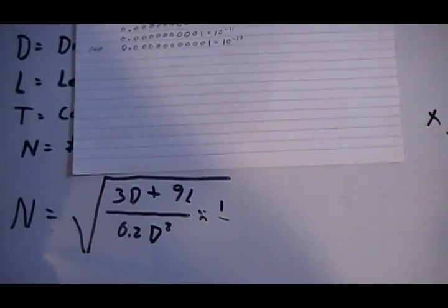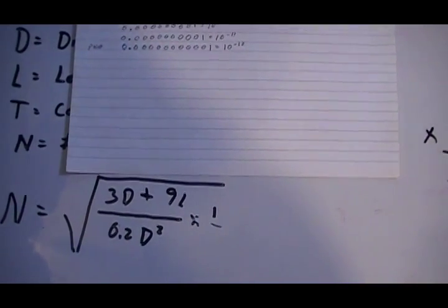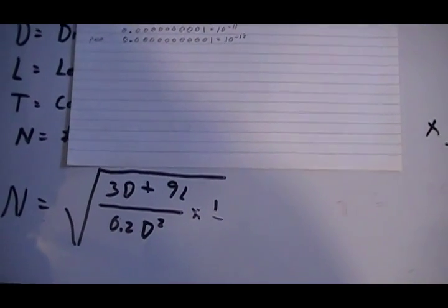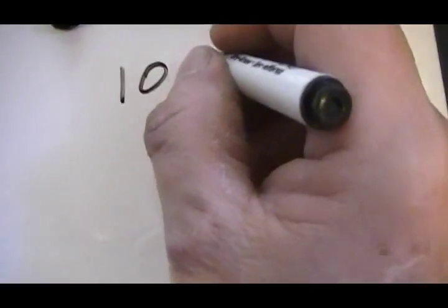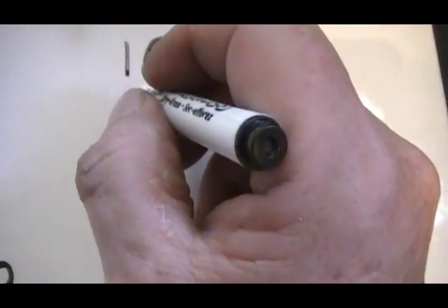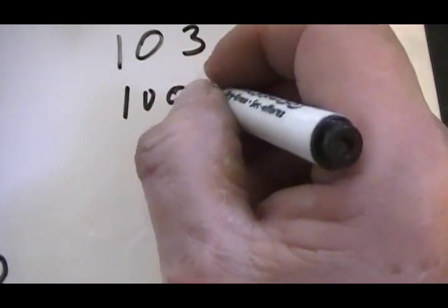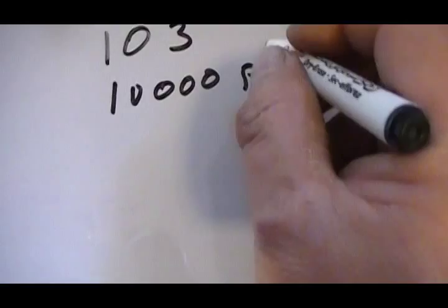Now, I'm going to do another video on this because this is kind of important, because one thing that this really picks up on is, and I know some of you have troubles with, because I've heard it, capacitors that just have a number marking on them, like 103. What the heck does that mean? And 102 and everything like that. Well, 103 is nothing more than this: if you got a capacitor that says 103, you take the 10, add 3 zeros to it in picofarads, 10,000 picofarads.